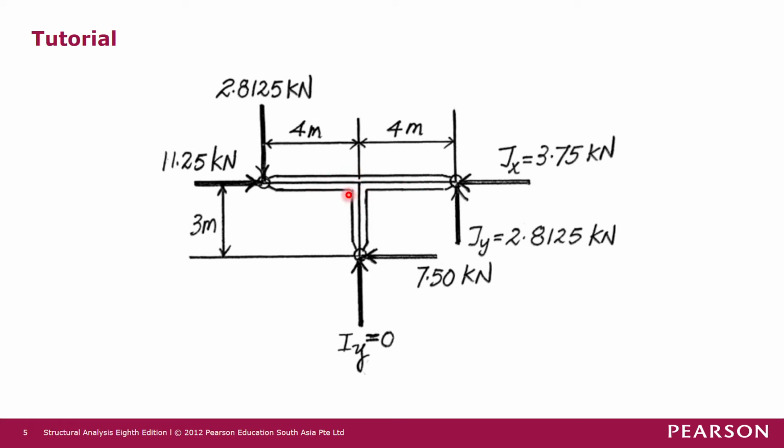So E, we're not detaching it away from the frame, so this one remains as a joint without any external forces. Okay, and then for joint J, we detach it away from the hinge, so we have a horizontal force and a vertical force which are unknown, so we name them Jx and Jy. And then Iy, we also don't know in the first place. And then at joint J here, we have 2V, so 2V is 7.5 kilonewton.